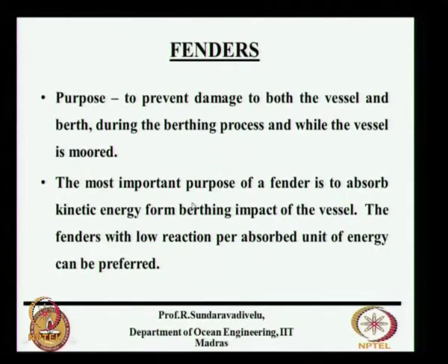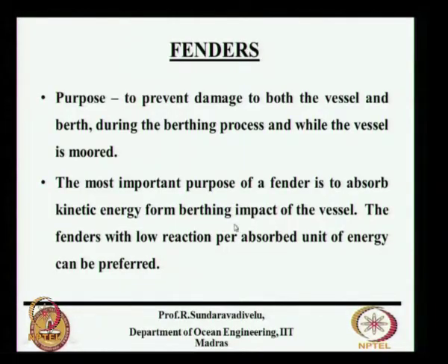The most important purpose of the fender is to absorb kinetic energy from berthing impact of the vessel. The ship does not have any brake, so it will reduce the velocity and it will be assisted by tug and it will go and hit. So, there will be an impact, berthing impact. Whatever is the kinetic energy at that time, that should be absorbed. For that we provide the fender.